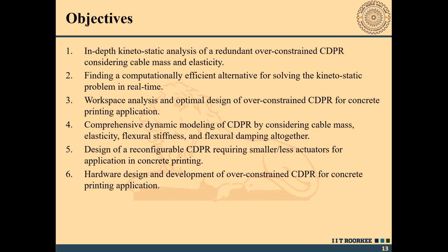Although if you are moving your bot at a slower speed, dynamics is not that important, but if you move it at greater speed, then one needs to have an idea about the comprehensive dynamics. So, we tried to do the comprehensive dynamic modeling considering cable mass, elasticity, flexural stiffness and flexural damping all together.